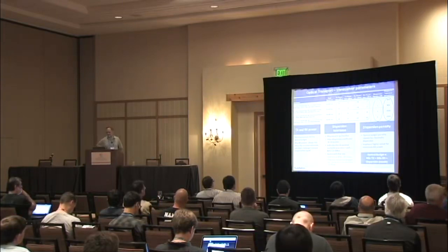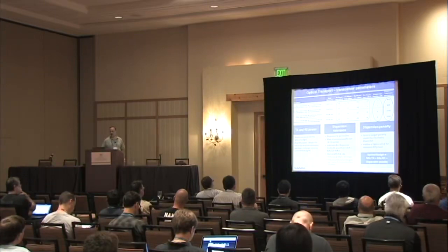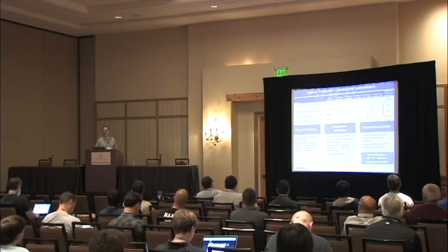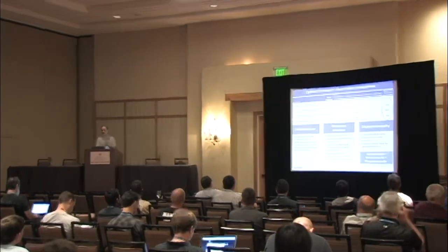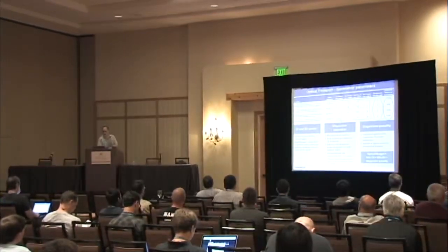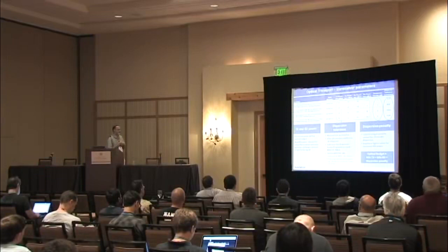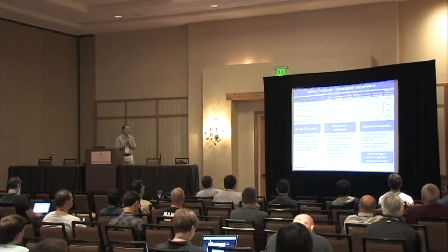Now, the dispersion, using this dispersion tolerance of a native dispersion tolerance of a fiber, causes indirectly a lower optical budget. You have a dispersion penalty, which in a sense lowers the level of sensitivity of the receiver, because the minus 16 and minus 23 is measured when you have no fiber in the middle. It's what is called back-to-back. So now your optical budget is the minimum transmit, minus the minimum receive, and minus the dispersion penalty.